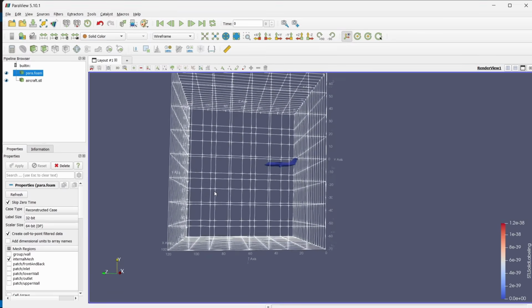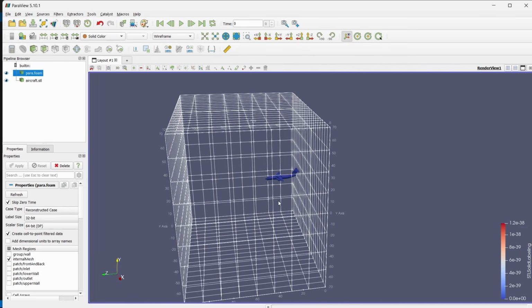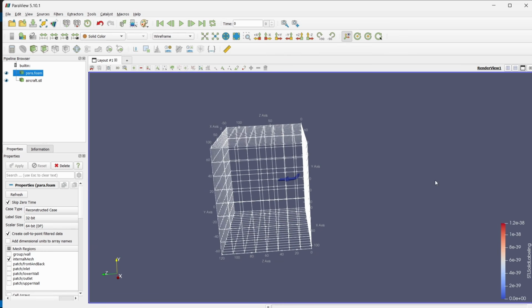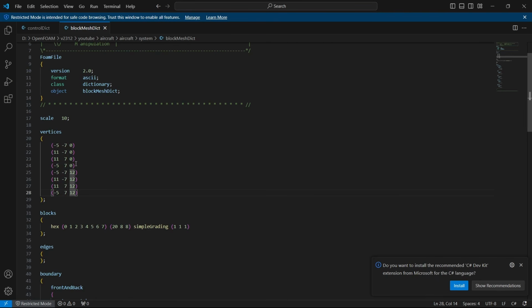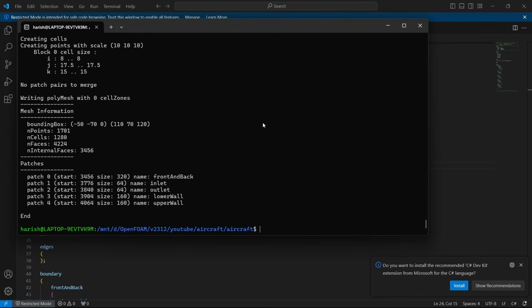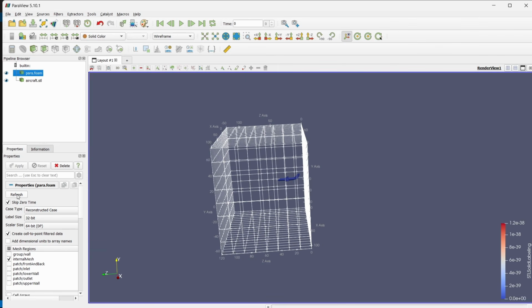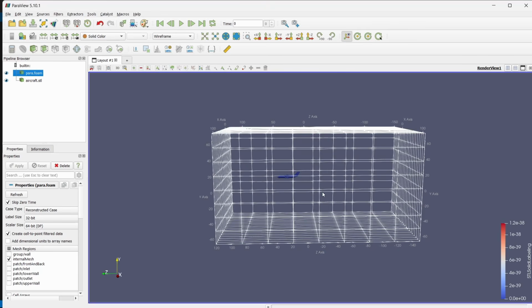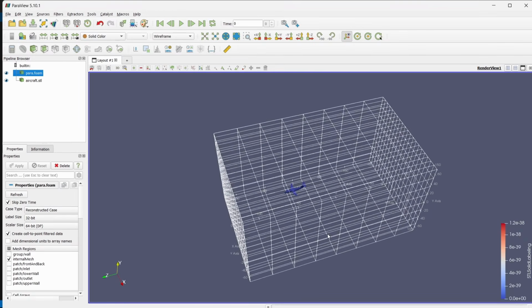Okay, now we have some decent distance from the nose. On the trailing edge also, we are bound to make a longer area of fluid domain. So I will go here and instead of 0, we are going to have something around -15. Again, this is just an assumption, just to see how well it goes. If it is not sufficient, we will again change it. See, now this is okay. It's not too big, it's just okay.